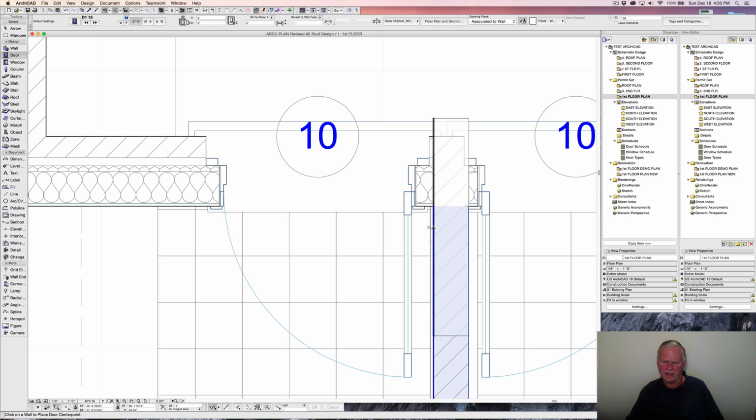So out of curiosity, let's just hover over this, get our guideline. And if we bring our guideline to right there, there is the opening, and that's set for a stud cripple 3 inches. But for some reason, this one didn't get set that way, because there's 1.5 inches. So we're going to pull this over and go D 3 inches